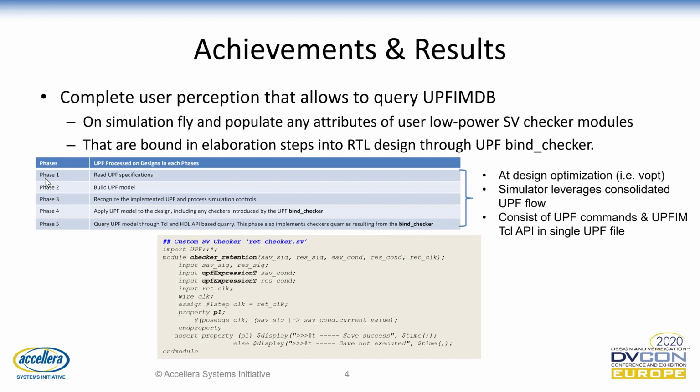that we confined into a single UPF file flow, which also covers the execution, elaboration, and compilation of the design. The bottom of this diagram shows the SystemVerilog checker, which is contained within a module and end module. You can also insert properties and assert properties within this module and end module, just like a regular SystemVerilog checker.